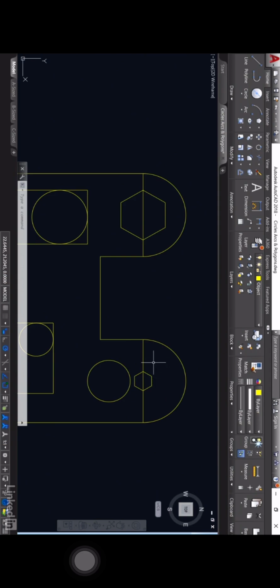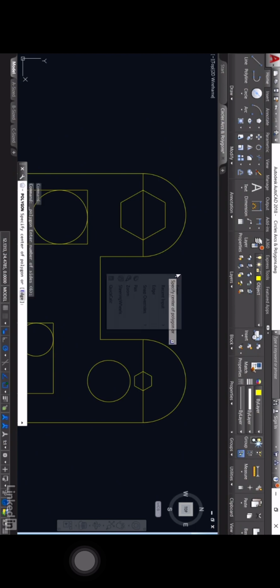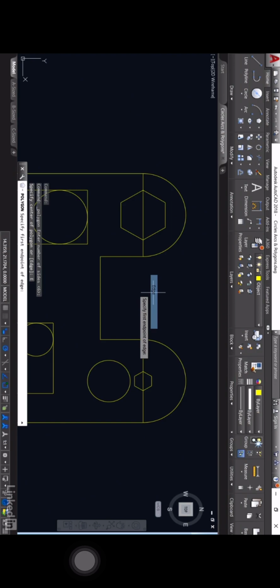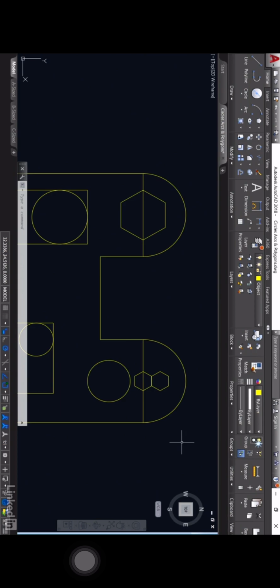So what I'm going to do now is use this edge, this polygon I've just created. I'll go back to the polygon command, stick with 6 sides and press enter. I'll now right click and select edge, and using my object snaps, I want that endpoint to that endpoint to form the edge of the 6-sided polygon, and there again is a hexagon all drawn up neat and tidy using the polygon command. Now I've used some very simple examples here to show you how to draw circles, arcs and polygons in preparation for your AutoCAD Certified Professional exam.